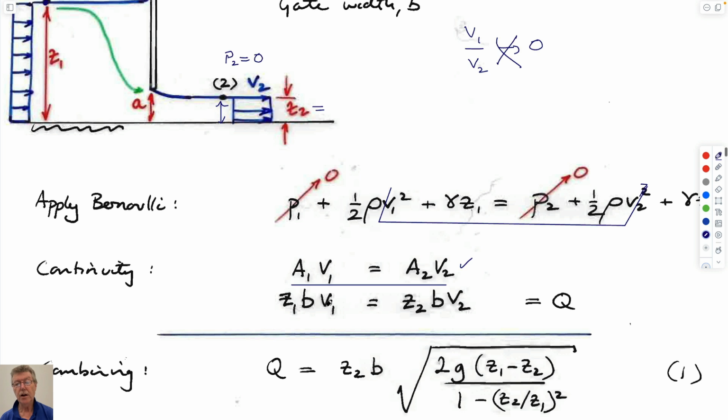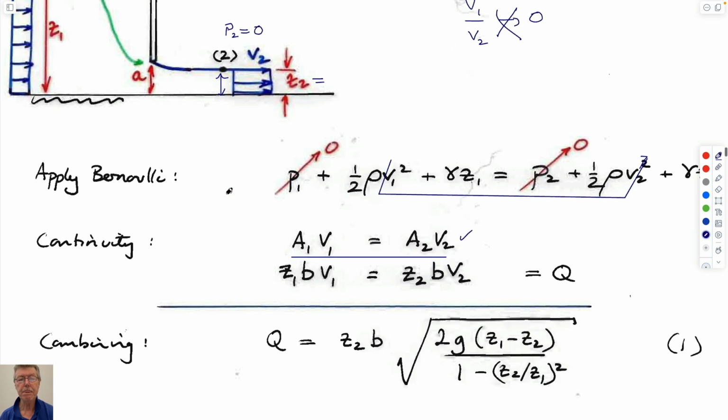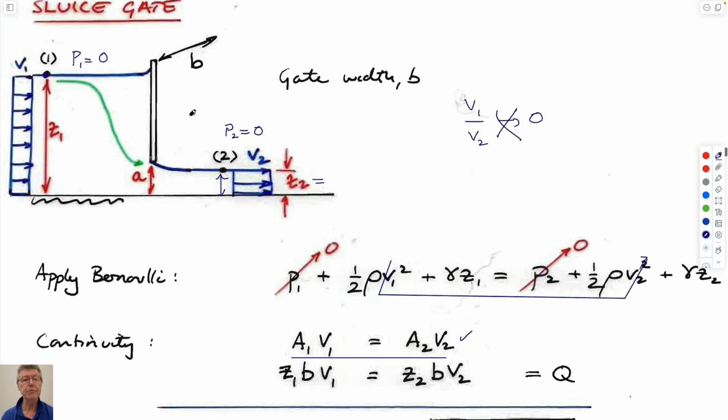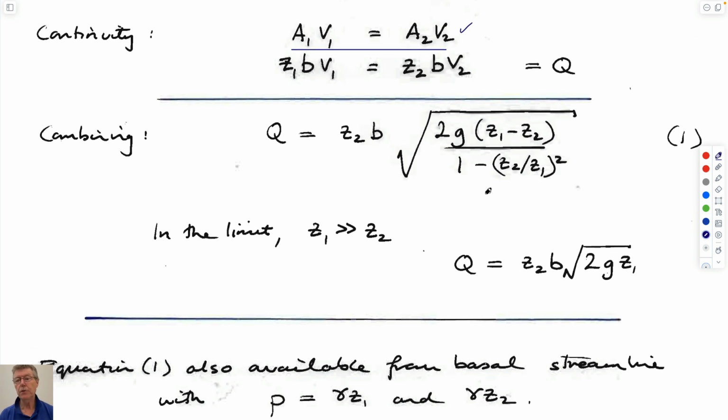And if we multiply velocity times area, we get volumetric flow rate. It's steady state, so the flow rate going into our control volume has to be the same volumetric flow rate coming out, a requirement of Bernoulli. In other words, a snapshot of this now and in 10 minutes, this is the same velocity here, this is the same velocity and height here. And if we manipulate it, we get something not very different from what we had before.